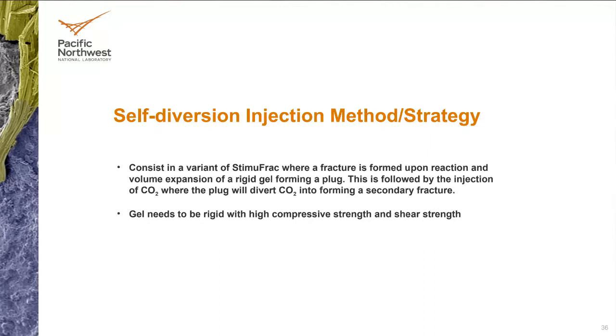So one way to do that is, like I say, the polymer alternating gas, or water alternating gas. In the case of polymer, PAG is polymer alternating gas. It gets fresh CO2 and fresh polymer solution going towards the tip of the fracture and continue propagating the fractures. And that's something that we can only do in the field. We cannot test it. It's really hard. We try, but it's really hard to do in a rock sample of a square foot.